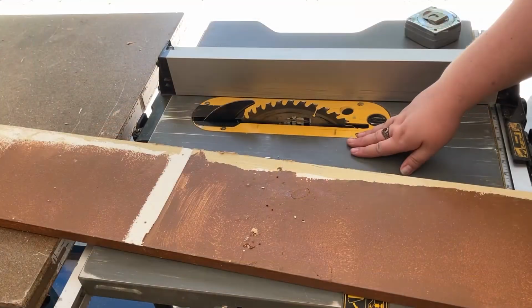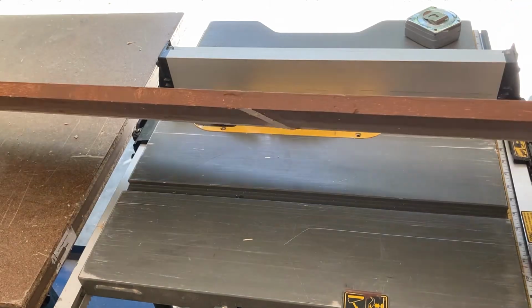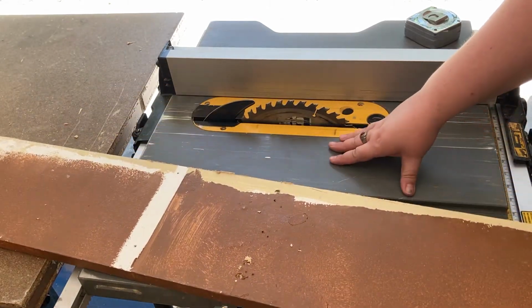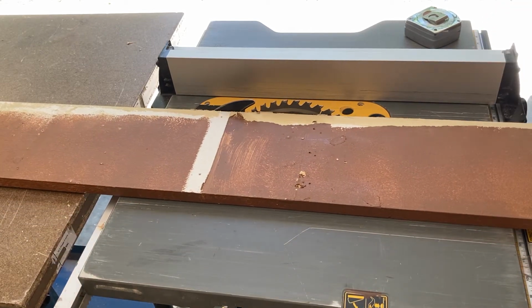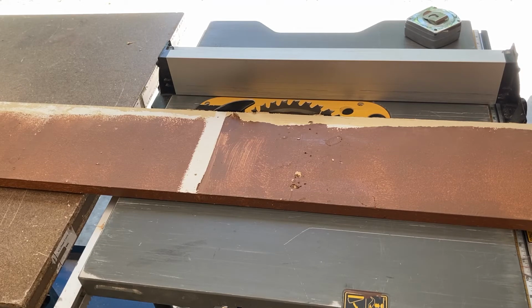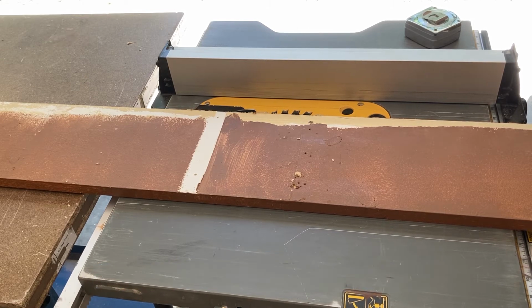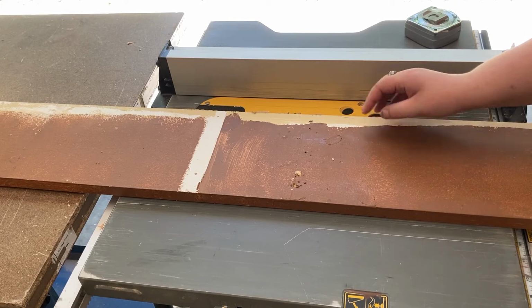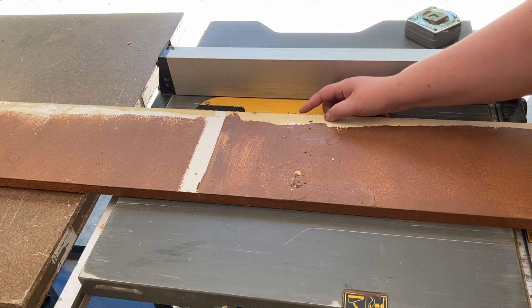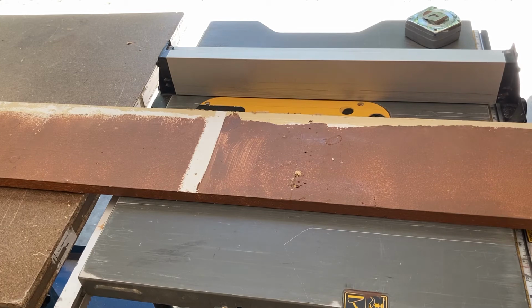We want to set the blade to an appropriate depth for the material we're cutting. 1 by is only 3/4 of an inch thick. So I've set the blade extra high just to illustrate what I'm doing here, but you'll always want to kind of nestle your stock right up to your blade, and you can lower that blade until you see the teeth just barely poking up above. You can see there's just the tiniest bit, maybe only 1/8 of an inch of blade coming above the surface.